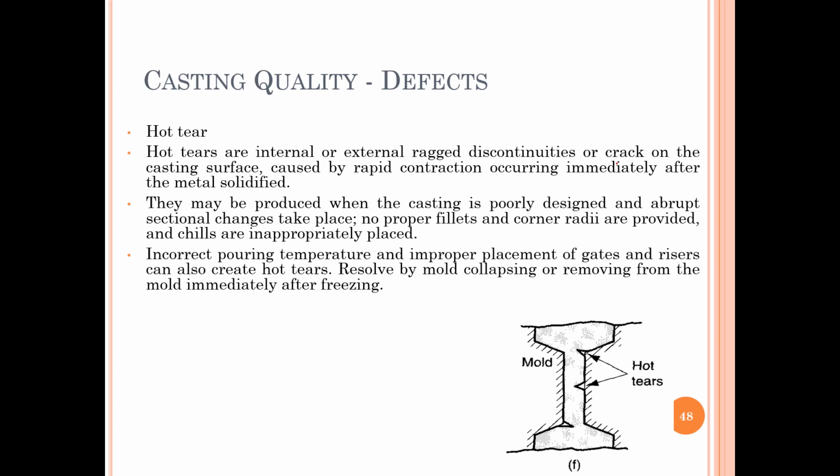Last one is hot tear. Hot tears are internal or external discontinuities or cracks on the casting surface caused by rapid contraction occurring immediately after the metal solidifies.